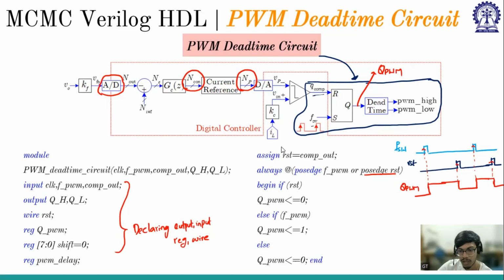So when we say blocking and non-blocking, they should be inside a particular module. But if I say if x1, some statements, else if x2, some statements. If the blocking and non-blocking statements are within this block, then they will happen at a time. And if they're within this block, then they'll happen at a time. But the line here and the line here will not happen at a time, because it depends upon if x1 else if x2, because else if x2 will only be entered if x1 is false.